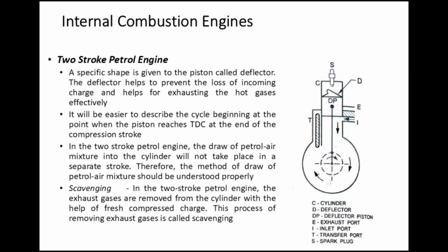of the compression stroke. In the two-stroke petrol engine, the draw of petrol air mixture into the cylinder will not take place in a separate stroke. Therefore, the method of draw of petrol air mixture should be understood properly. Scavenging. In the two-stroke petrol engine, the exhaust gases are removed from the cylinder with the help of fresh compressed charge. This process of removing exhaust gases is called scavenging.